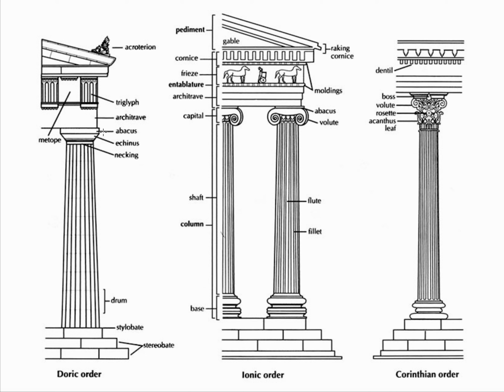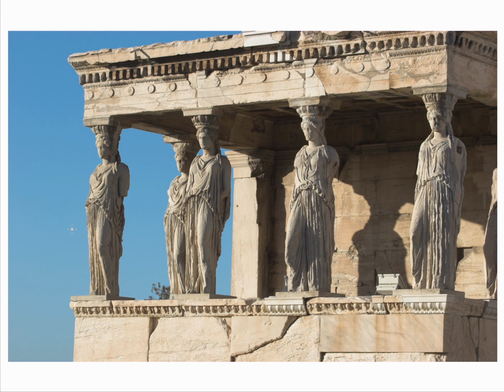And so it has to do with how the loads are transferred on top, how they're transferred at the bottom, even the width or the entasis of the columns, which tries to allow for buckling. So again, as we've seen in other things, there's this combination of not just the intent of what the structural element is from a design perspective, but then the constraints that come through with construction and its technical behavior. I love this particular slide as it shows a sort of embodiment of the figure as a column. It helps us to then visualize how those forces would come through.